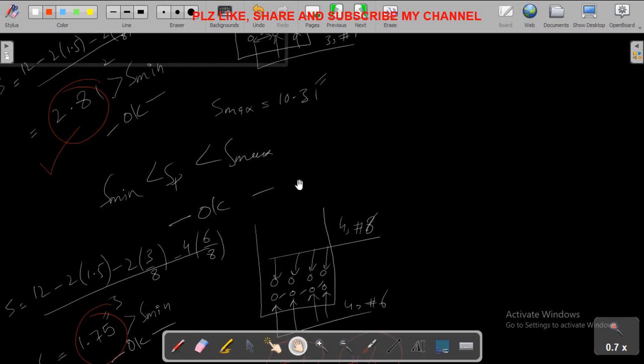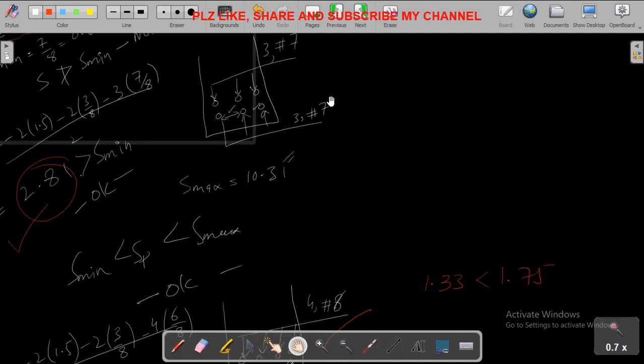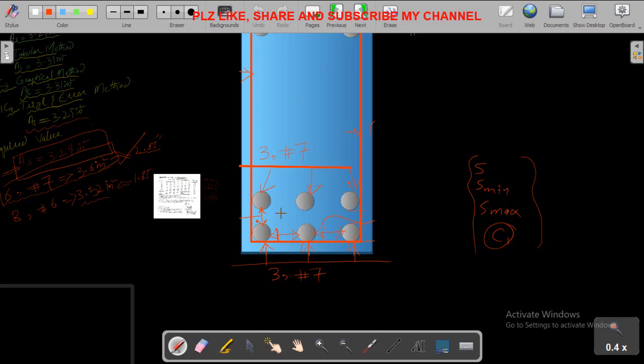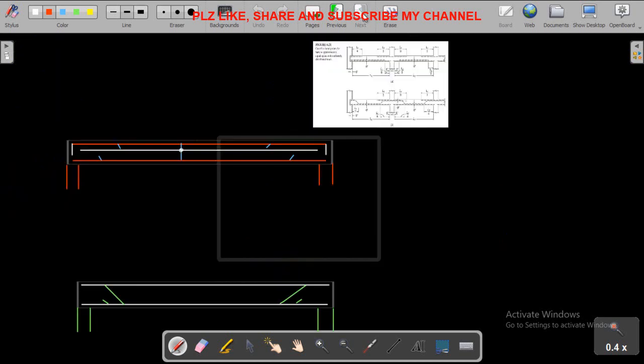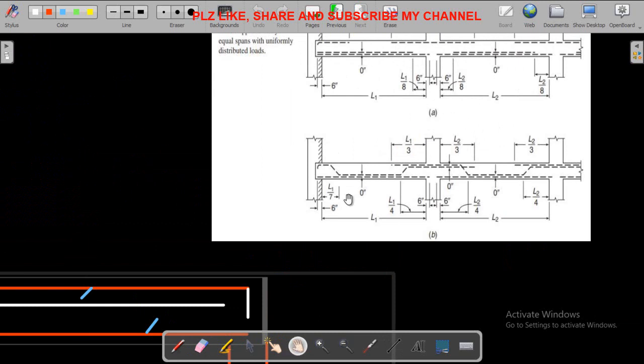So both arrangements are okay, because the lateral spacing in between the bars which is needed is 1.33 inches, which is less than 1.75. So we can use either this option or this option. Both options are okay, right? So this is the final cross section, and let me draw the longitudinal cross section. I have already discussed this graph in my previous part.